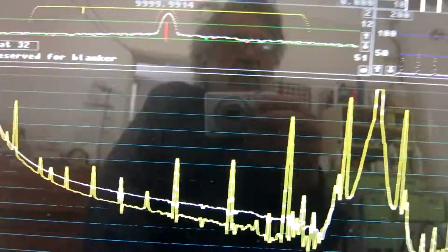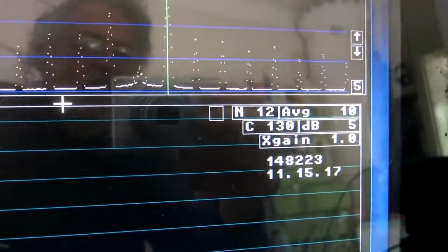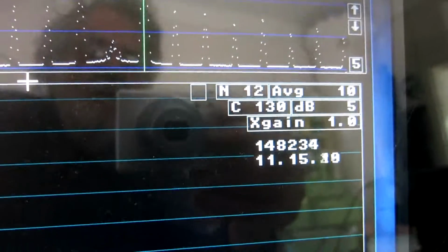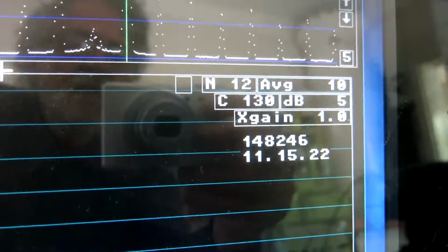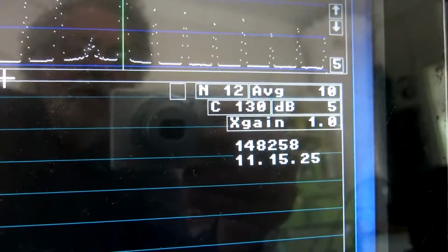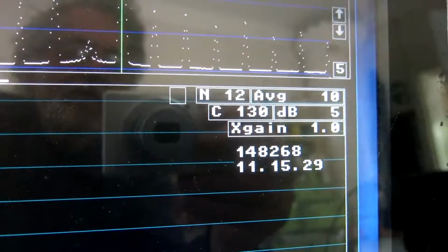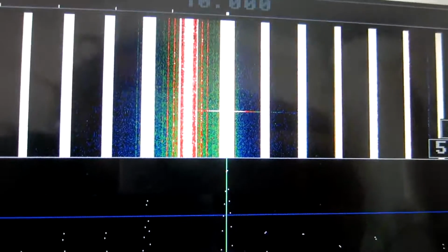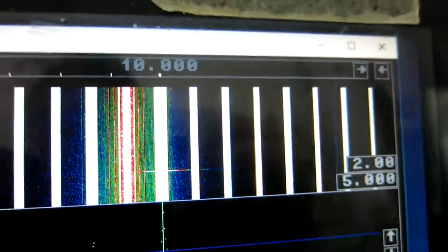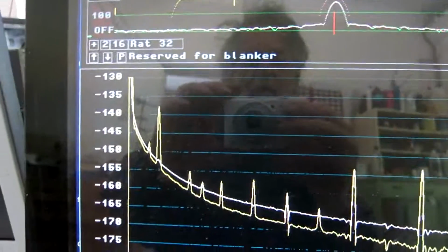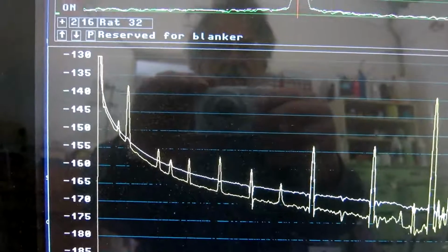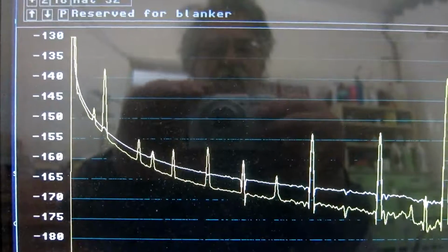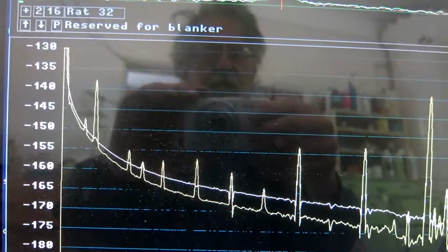I have inserted 10 dB of attenuation on the input and also reduced the attenuation on the output by 10 dB. So now the oscillator amplifier gives 100 milliwatts at the output, and glitches, narrow band noise pulses, are still present. You can see one here. They seem to occur less frequently though. And I will read the values from these curves and take down on my note sheet.